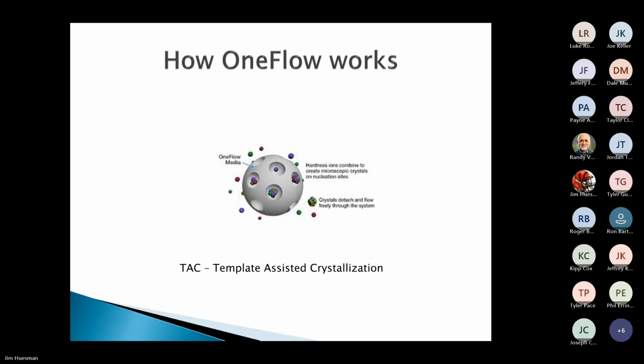How we're doing that is, well, we talked about the media in a softener actually grabbing on and holding on to our calcium and magnesium. We're holding on tight to it. Then after a certain amount of time or gallons, we self-clean it. We regenerate, and we send all of that calcium and magnesium to the drain.